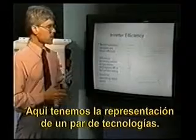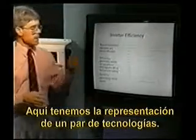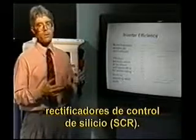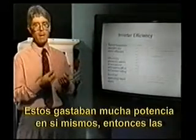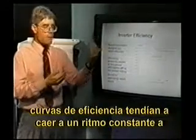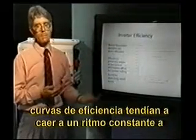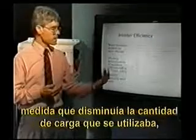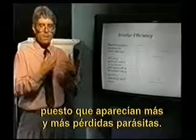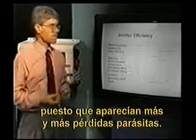We have a representation of a couple types of technology. In the past, inverters were made with silicon-controlled rectifiers, or SCRs. These used up a lot of power themselves, so the efficiency curves tended to simply drop down in efficiency on a steady basis as you decrease the amount of load that was being used, because more and more of the parasitic losses were showing up.